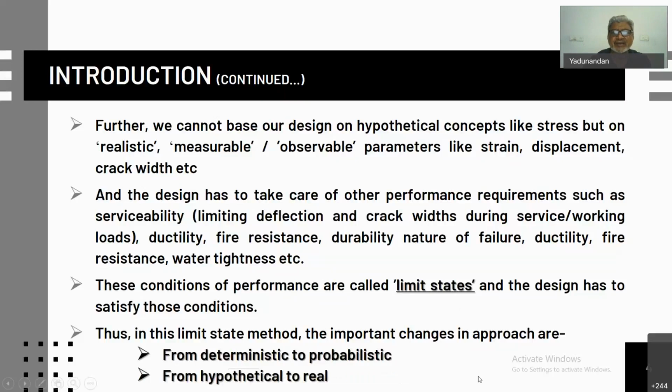And the design has to take care of so many other performance requirements, such as serviceability, that is, limiting deflection and crack widths during service. Ductility: the failure has to be ductile. The structure has to give sufficient warning before failure.